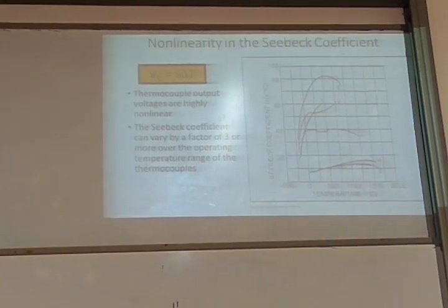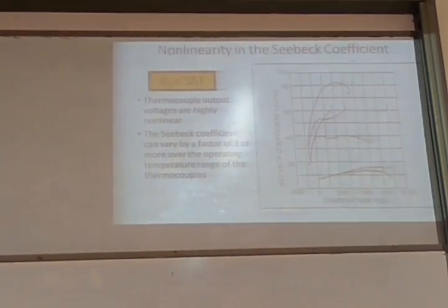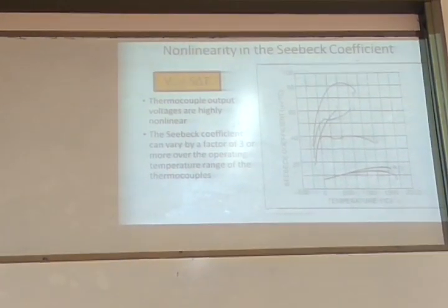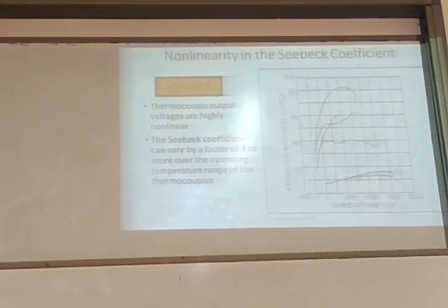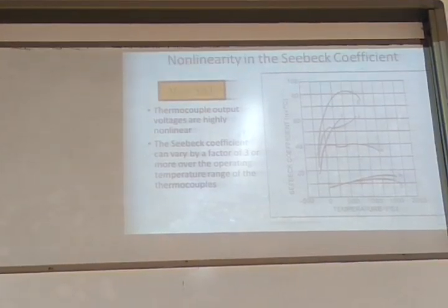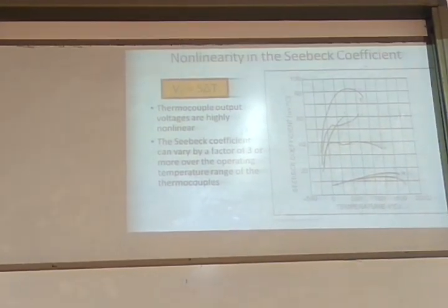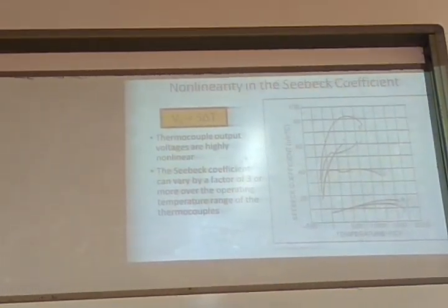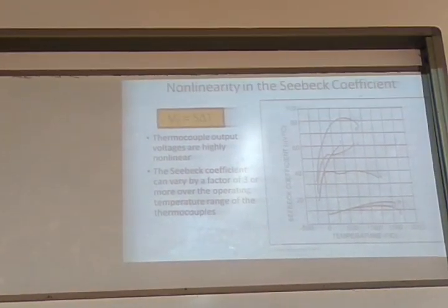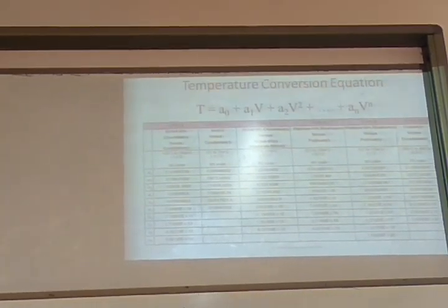In a particular range, that non-linearity will be minimal. Either we use it only in that particular range and ignore that small non-linearity, that's one way of using the thermocouple, or we should have good computational resources inside to compensate for that non-linearity and get a linearized output if you are using it for the entire range.